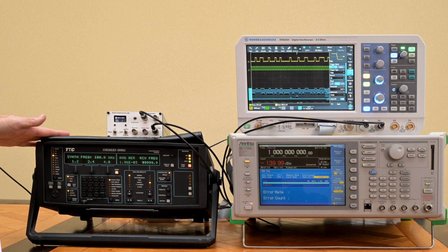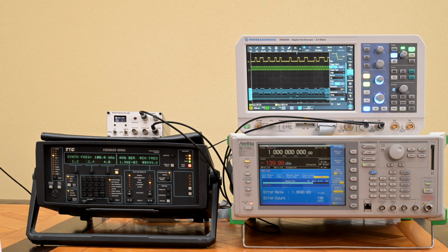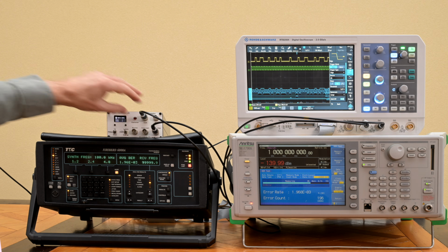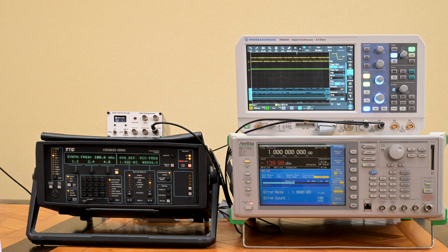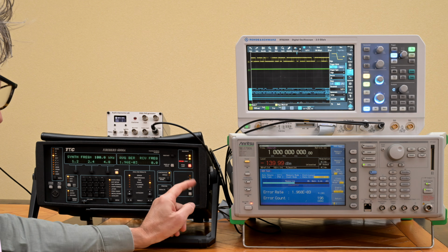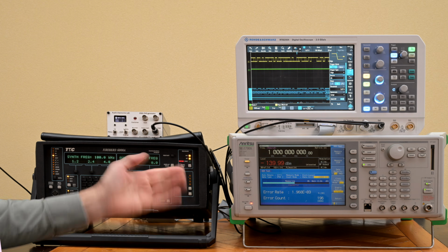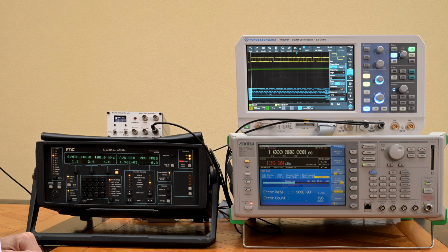However, this can play a special trick that the Anritsu is not able to, and I'm pretty excited about that. Because now we're feeding the devices both data and clock signals, and that is what most BER testers expect. And if I disconnect the clock signal, then both of them basically don't work anymore. My Anritsu stopped, and my Fireberd basically says no clock, and the sync lost light is burning, and even if I press it, there's going to be no resyncing going on. The receive frequency went to 0.